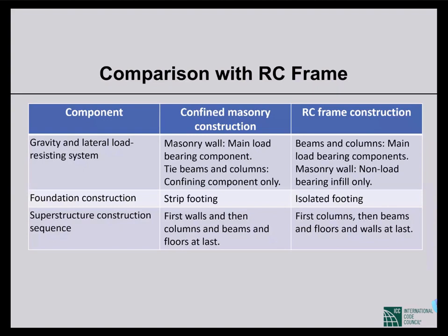So in places where we don't have the luxury to go for reinforced masonry, at least, or if the building owner cannot afford a regular RC frame structure, who would like to make unreinforced masonry, they can build this kind of confined masonry without much added expenditure. So that is the advantage.